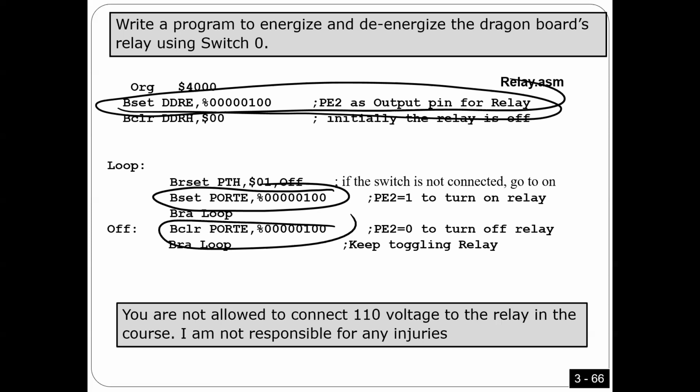It's the same thing in C language. In C language, you can do the same instruction like this one. You got what I'm saying? You can say DDRE is equal to like 0xFF, right? Or if you want to change some bits, you can use AND or you can use OR. It's exactly the same thing.